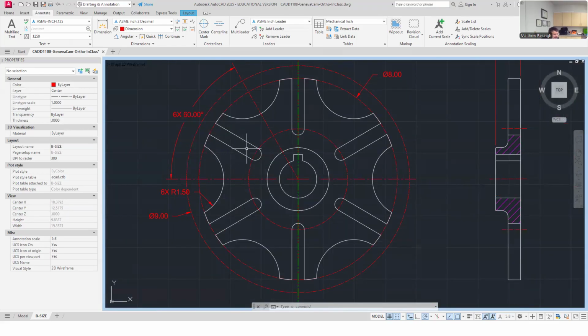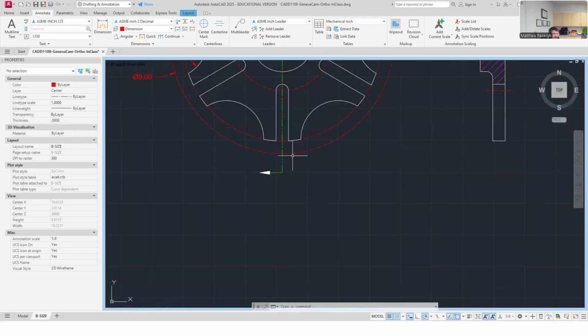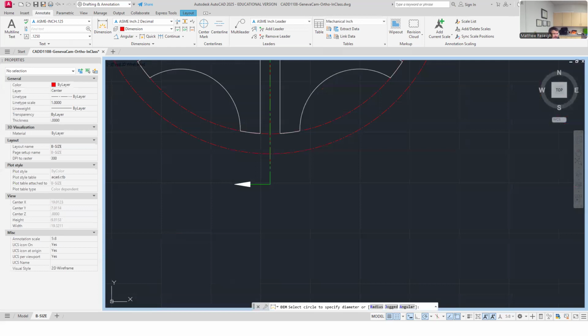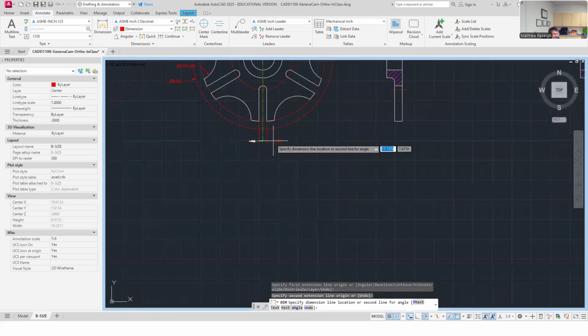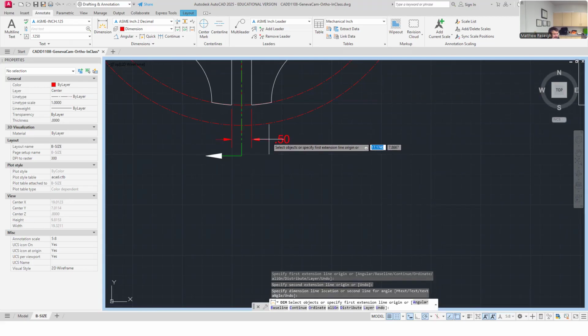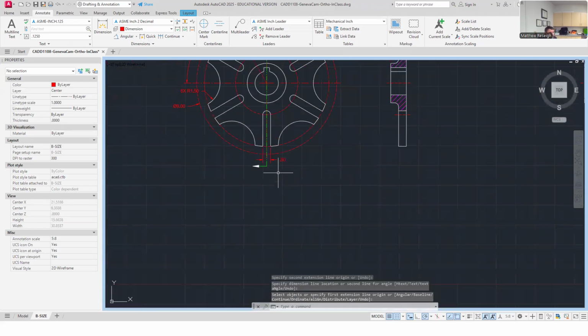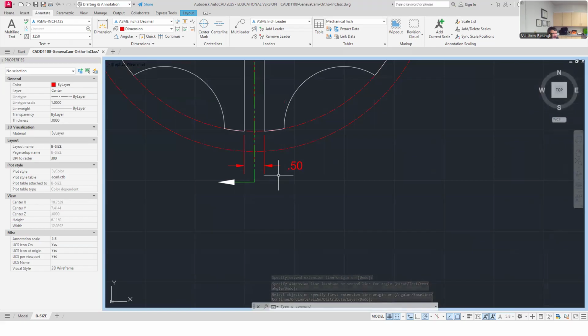Now I've got the slotted features on this next one. So let's dimension those for size and location. So the size, I think on my print, which kind of caught me off guard because I kind of forgot that I had sized it down here. And I had sized it with a width like this, it's a 1/2 inch wide. And I'm going to pull this. I might interfere with my arrow and I might have to extend my arrow a little bit longer. That's okay. But I think this was a 1/2 inch wide.